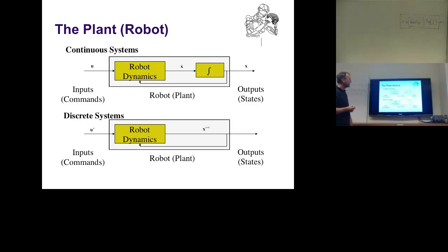Now, continuous systems means we're doing continuous time. For discrete systems, we do time steps, delta t, which is much more natural for what's going to happen on a digital computer when you implement it, since you usually have to run things off a clock. The digital computer, in the end, is not a continuous machine, although it can approximate continuous differential equations pretty well if you discretize the time step small enough. In robotics, we usually run control systems between 100 Hertz and 5 kilohertz. These are significant time steps, and discrete systems actually matter. You will see in one of the next lectures how the change from a continuous system to a discrete system makes a big difference in how stable a system can be.